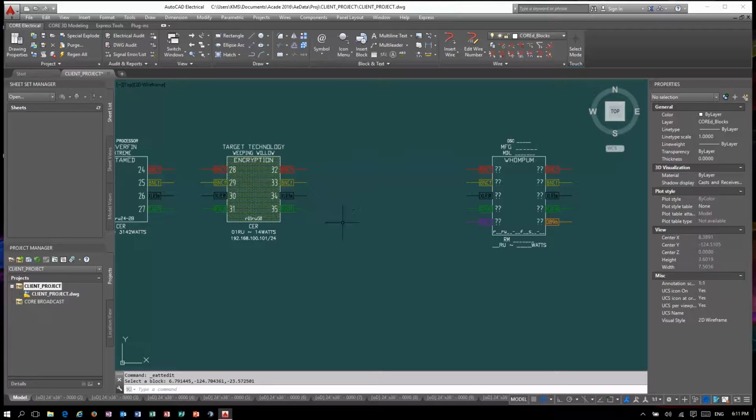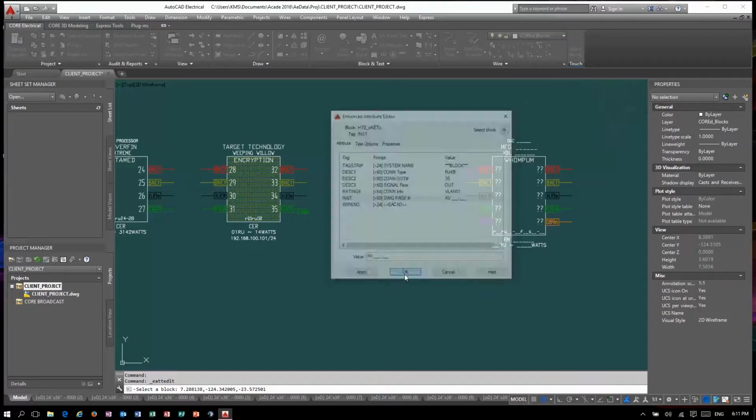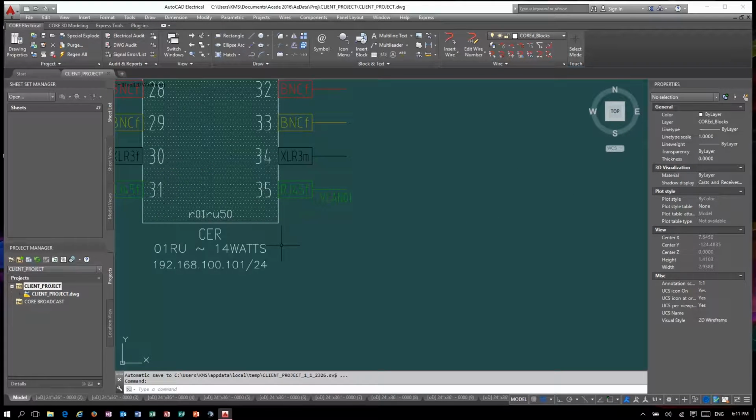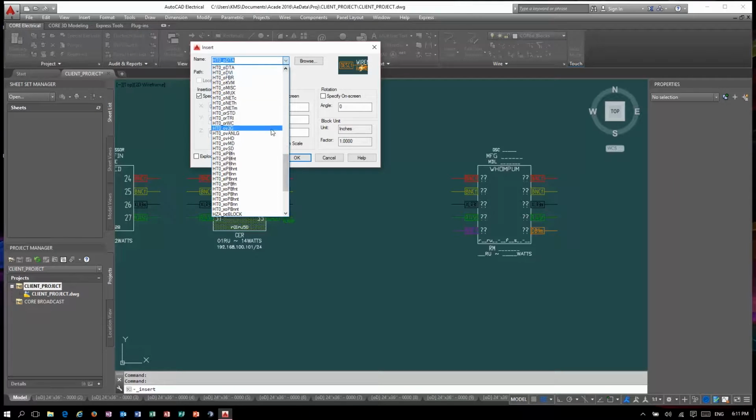We hope this demonstration showcases the versatility in modifying the style and color of equipment blocks, signal type and functionality of connectors, automatic wire numbering on a local or global scale, and the use of special connectors to create signal converters and adapters for wire number pass-through.